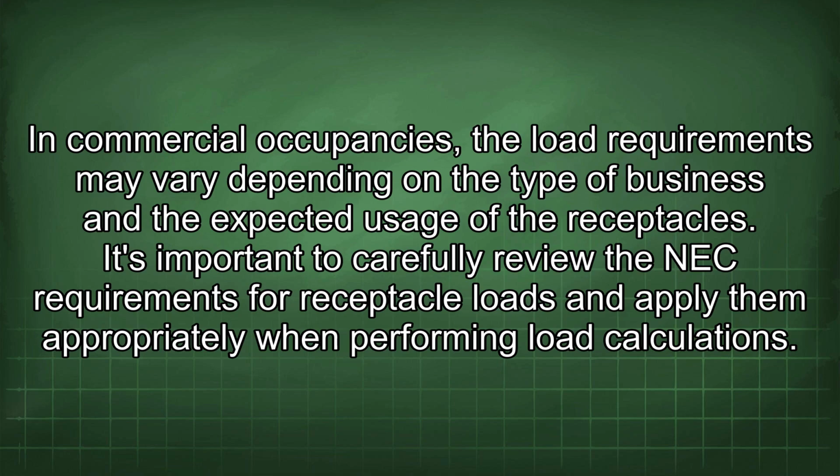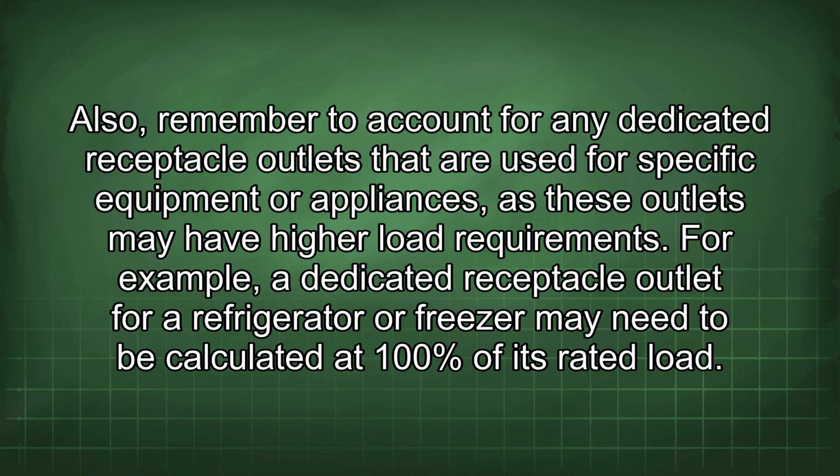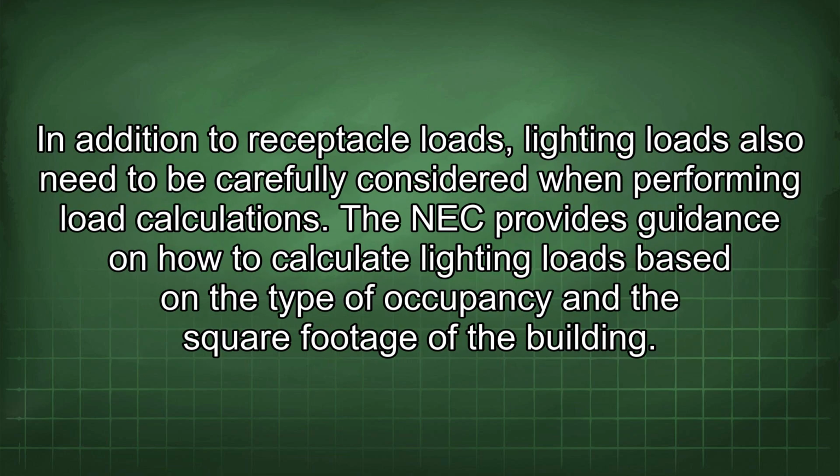In commercial occupancies, the load requirements may vary depending on the type of business and the expected usage of the receptacles. It's important to carefully review the NEC requirements for receptacle loads and apply them appropriately when performing load calculations. Also, remember to account for any dedicated receptacle outlets that are used for specific equipment or appliances, as these outlets may have higher load requirements. For example, a dedicated receptacle outlet for a refrigerator or freezer may need to be calculated at 100% of its rated load. In addition to receptacle loads, lighting loads also need to be carefully considered when performing load calculations.